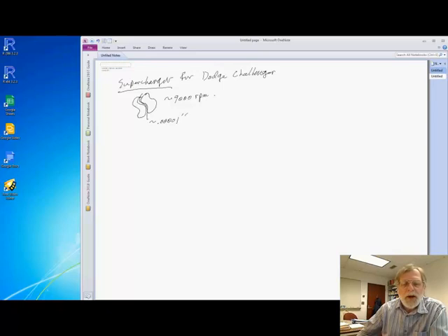So nobody dared offer a supercharger on a car because they knew they couldn't hold the tolerances in a production setting and that they would have lots of failures, until very recently. Now the tooling is really good. I bring this up because the difference between the upper and the lower spec limits has got to be really tiny.